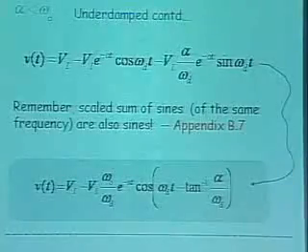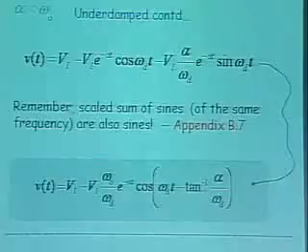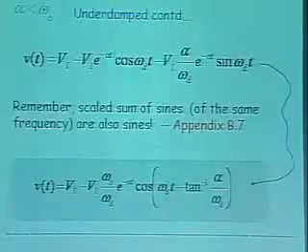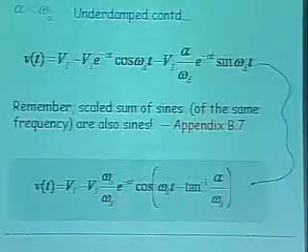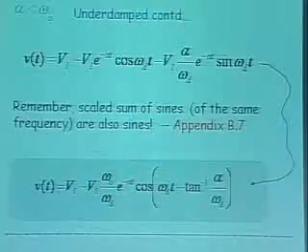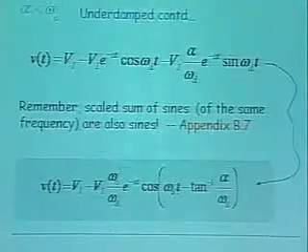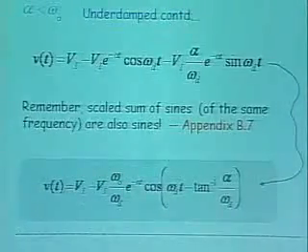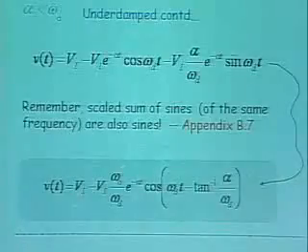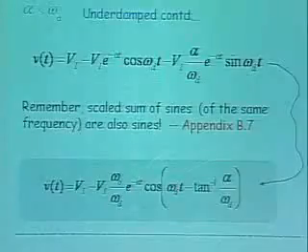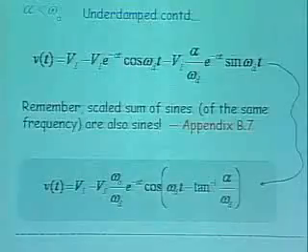Okay. Again, to pull the Feynman trick, if this alpha were to go to 0 here, then you would end up with the same expression you had for the LC situation. Okay? So let's stare at this a little while longer. There's a constant plus a minus a cosine term. So there's a sinusoid at the output, and there's an e to the minus alpha, which ends up giving you the decay you've seen before.